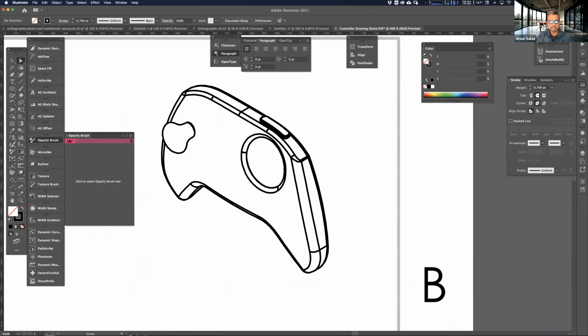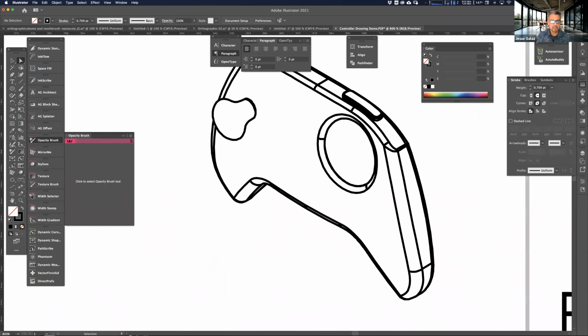And also, if you have an isometric view, don't forget to get rid of some of those fillet lines on there as well. Sometimes you may want to leave some lines, maybe something like this, where you show just a few of these lines to show that there's a radius there, but they don't actually touch. Just to show that there is a turn of a corner, but by not meeting these other lines, it shows that it's curved on that side.